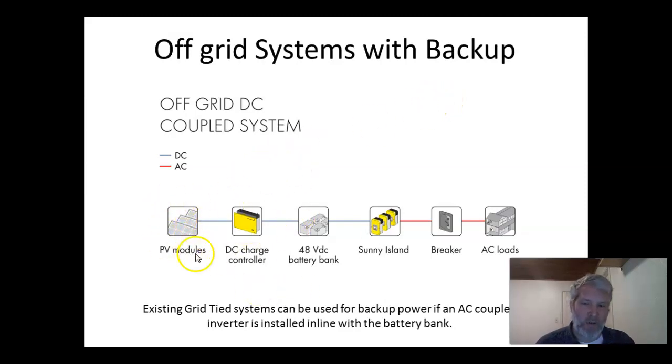You may have different modules that are being used here, but most of the charge controllers now are standard, and they can work within the voltage requirements that's needed for standard solar cells. But you may run into that. So if you are building an off-grid system, you need to make sure that you look at the charge controller's minimum and maximum voltage requirements, because it may run into an issue there. The same thing with the amperage.